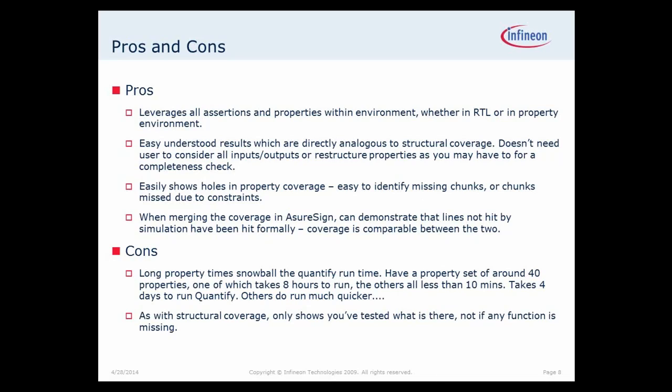What you would do, though, is run your properties until such time as they got to fail, stop. And I was also having problems running OneSpin if you had asynchronous code behavior. So typically you had to run all of your properties through once with none of the faults switched on, find out which faults passed and failed as a result, and then only use the ones which pass overall before running them through.